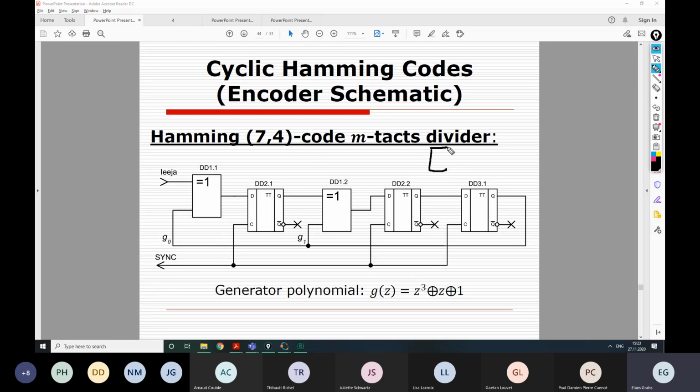So basically that would be OR, and we need to connect each of these outputs. So if any of those triggers inside has 1, then output will be 1, which will be the signal for error. If all triggers have zeros, then output will be 0, meaning that it's okay, no errors.